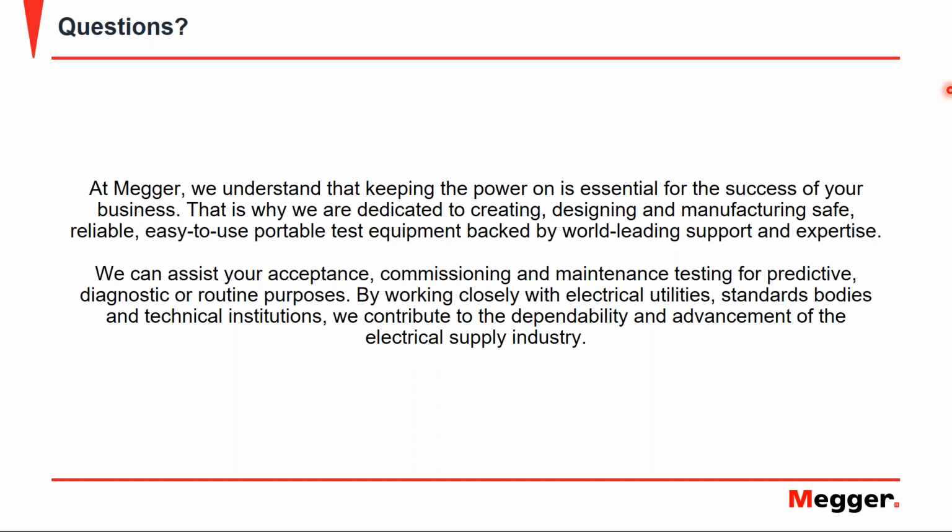I know that the IEEE 400.3 is now getting revised, and they will put in a limit for PD testing on XLPE cables. And there, they will focus on the extinction voltage. Depending on whether you have a load break or a normal elbow, the extinction voltage level should be higher than 1.3 or 1.5 U0. There will be limits coming for new accessories.